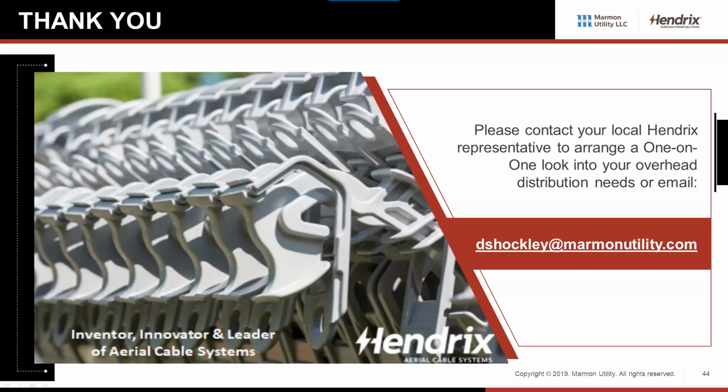So I always try to take a step back and look at what caused it. Lightning may be traveling down the messenger and looking for a deterioration in the covering. So I ask, what caused that deterioration? Was it man-made, such as removing the covering to make a tap? Well, there's already an arrester there. And that refers back to the initial question: if you get a lot of tree rub and it causes deterioration in the covering, that's another potential opportunity for a flashover.